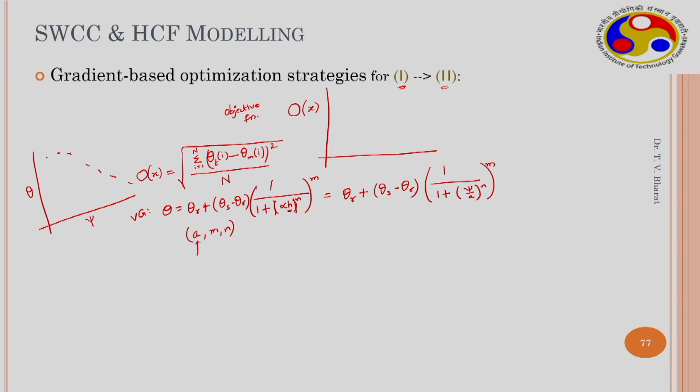If it is sandy soil, you can give say 2 kilopascal as an initial value. If it is a clay soil, you can give a very high value, say 1000 kilopascal or something, and you can give some values to m and n, maybe n equals 1.5 or something, and m you can give 2 or any value. If m and n are related or constrained, then you give the values accordingly. So, this is called the initial guess.